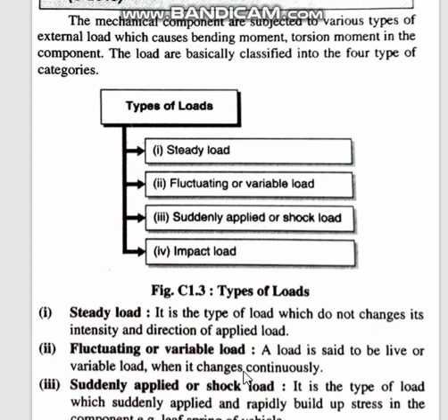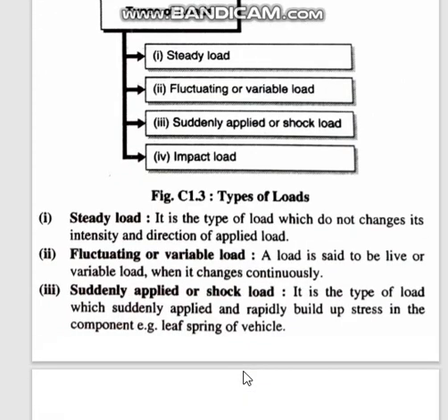Okay, and then the next one is the suddenly applied load or shock load. Suddenly applied load means, you see, suppose I put some weight on your head, but I have not yet left it. My hand is still holding it, and it is only touching your head. The load has not yet come upon your head, and the moment I release my hand, all the load suddenly comes on your head. That is suddenly applied.